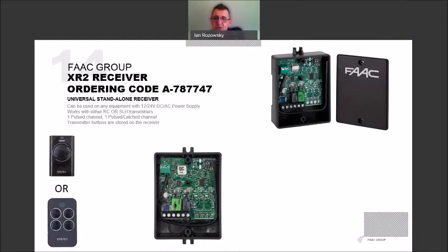Something that's worth mentioning is that up until now, the factory, when manufacturing these receivers, has been testing them with an SLH remote control. As a result, they haven't been erasing the unit after testing, and so these receivers have automatically been configured for use with an SLH transmitter. So there may be cases where you get to site, you try and program in an RC transmitter and it doesn't work. The reason is that there's already an SLH transmitter in the receiver, which makes it an SLH receiver.